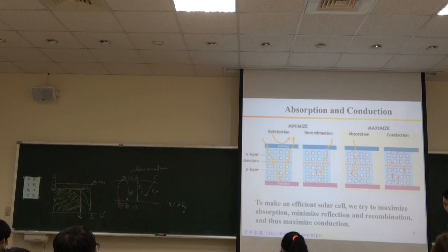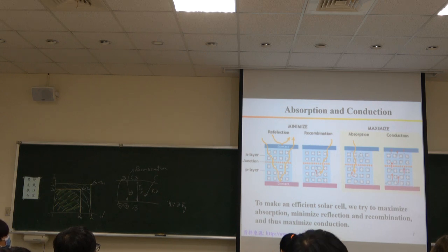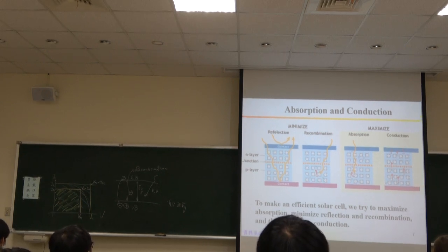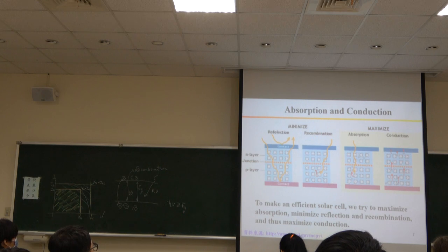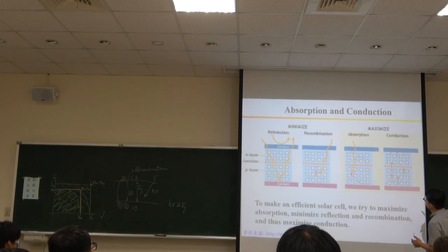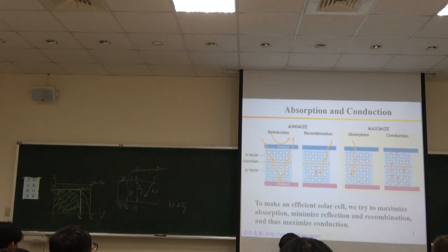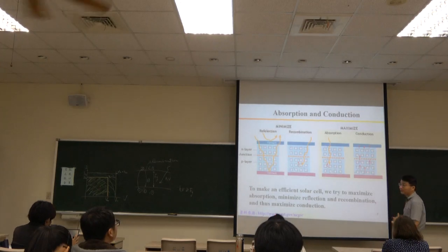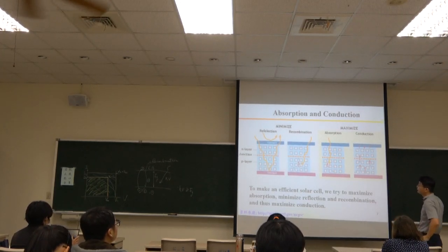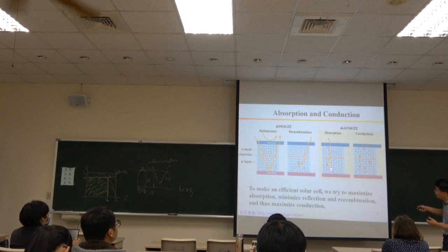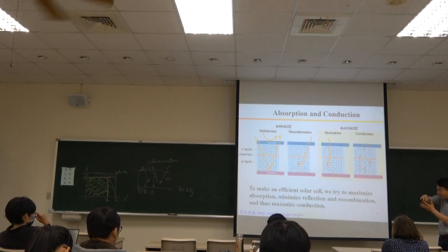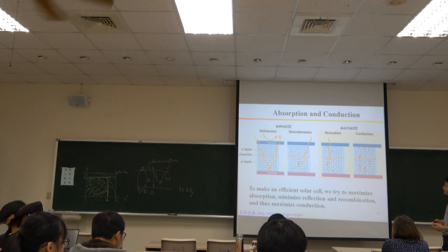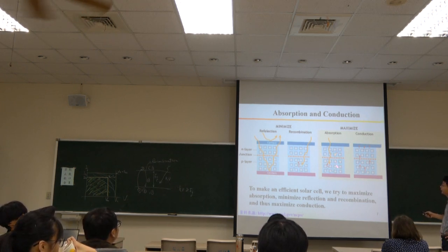Maximize absorption. For the material side, you need to create a wide band gap absorption, right? And also, if we can do something else to create a higher surface roughness, then the light could be scattered on the surface and highly absorbed into the materials. So therefore, the light has more pass through, more path to be absorbed into the materials and create high efficiency.